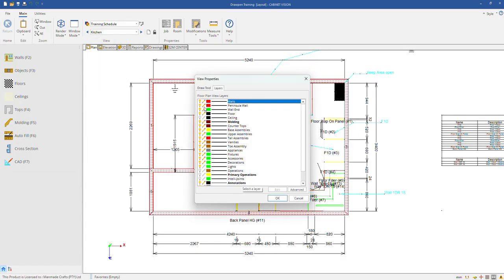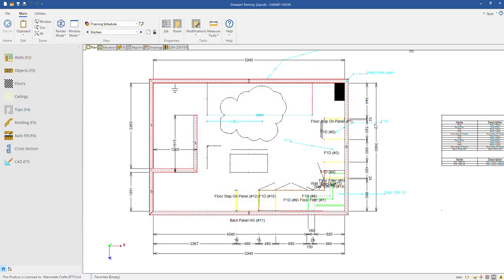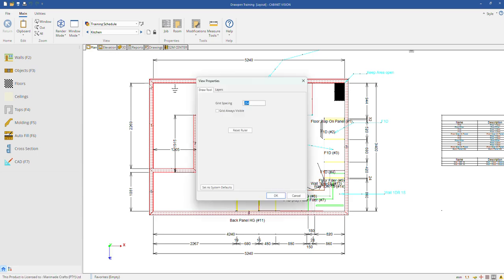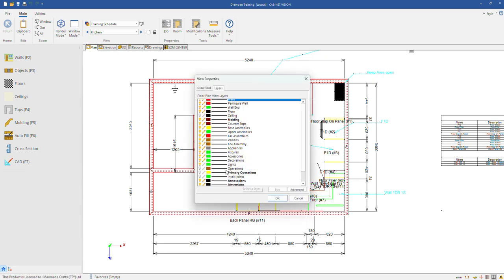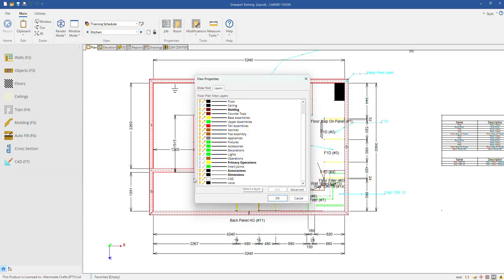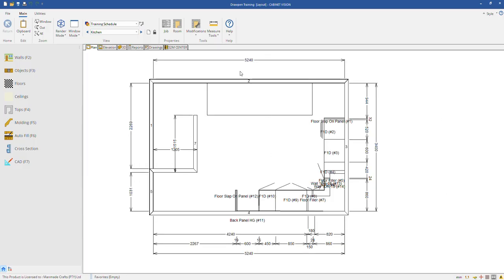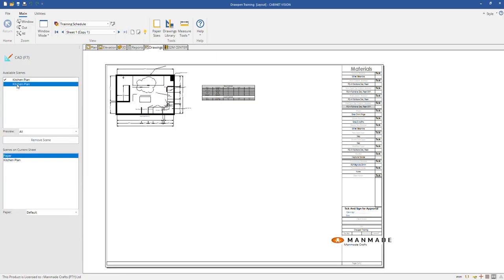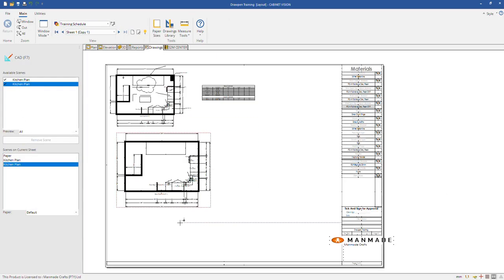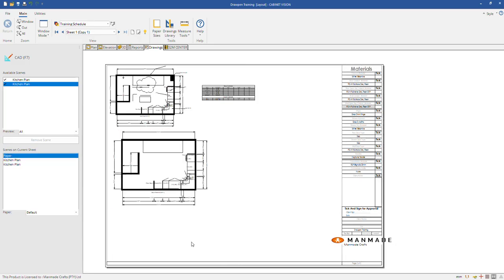You remember the little pencils? So you can switch that off to send to specify, because for instance, all of this DXF information is for me. I need it on the design, but I don't want to send it through to the customer. So I can go and say, I don't want to send the CAD through to drawings. Right click to drawing removes the CAD, and then I can bring in that clean image on my drawings.